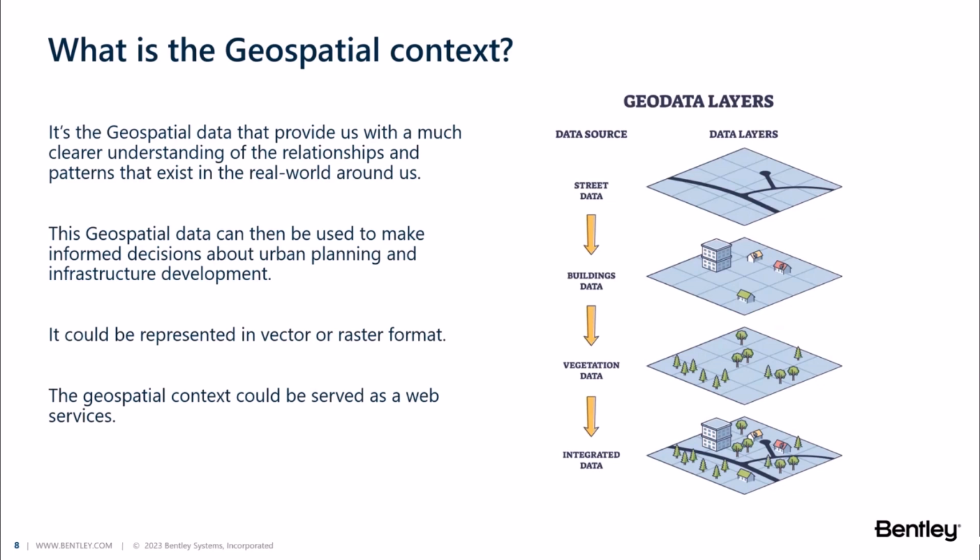It's crucial, yeah. Without understanding where the actual project is to take place, it's crucial that we set this up in the early stage and establish a geographical coordinate system within that design, so that any design works moving forward are in real world coordinates.